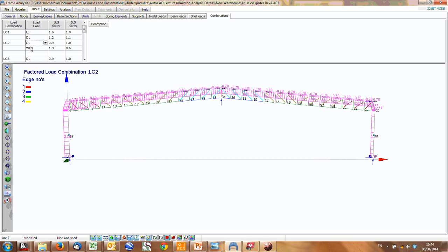But here we go. Got dead load and wind load, dead load, wind load, etc. So you've got various wind load combinations we consider here. These serviceability ones I just put in there to assist design, so you output serviceability forces and reactions, but you don't need to worry about that. Alright, but here we go.